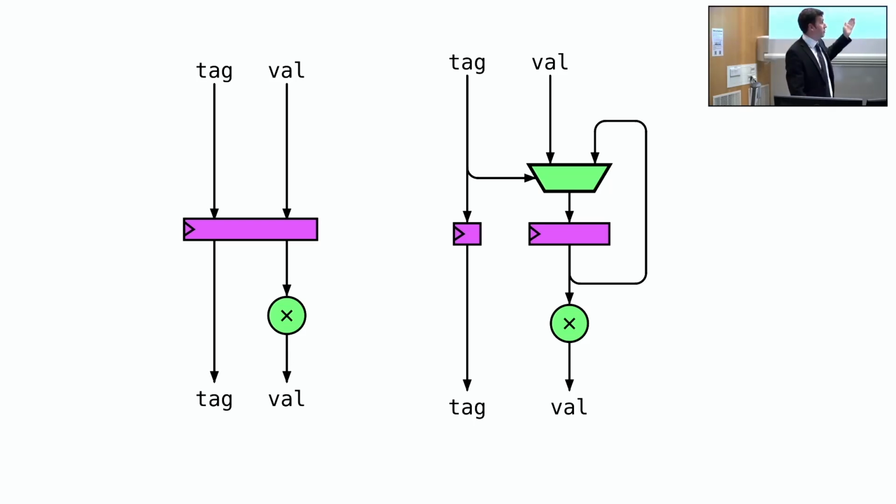One more thing before the results of performing this optimization. This is an optimization we could do manually, of course, but doing so for every register in the design will become very, very tedious after a while. And it also doesn't enable design space exploration. We have to commit to making this change if we want to make the change, but if it's a compiler optimization, we can simply turn that on or off depending on if it works, or if it gives better results. It will still produce the right results.